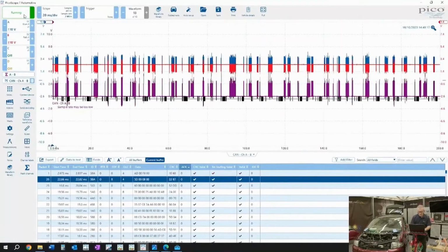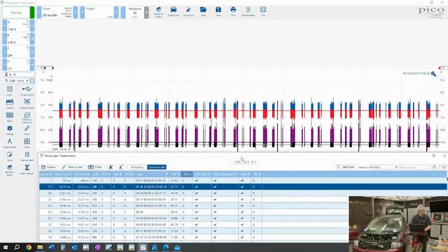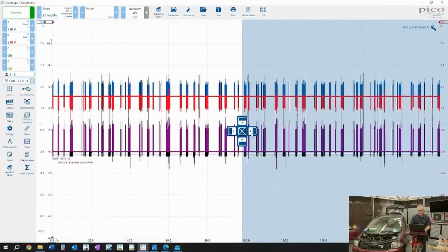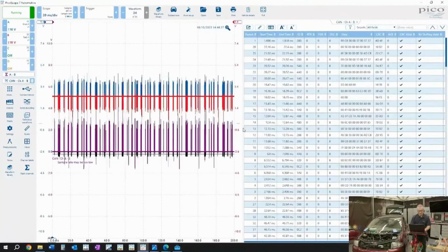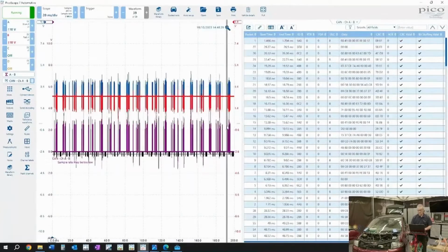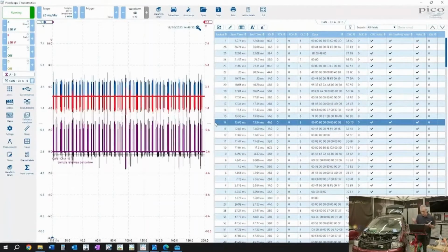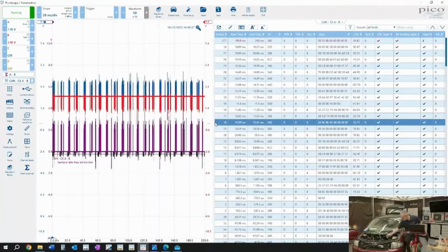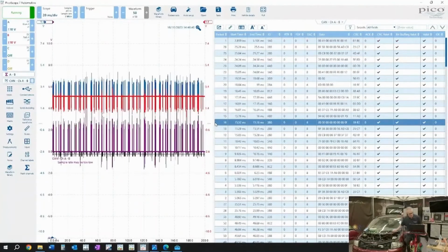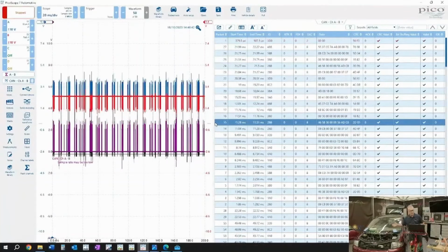In fact, something that Ben talked about was views. If I click on this here and drag this to the side, we'll be able to have our waveform on the left and our decode table on the right. Let me just bring that in. So we've got the entire table. Well, let's introduce that short circuit to ground momentarily and just see what happens to data. Now, I'm sure within there, we should have captured an error or introduced an error.